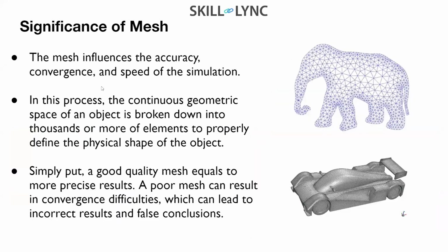Then, significance of mesh. Mesh influences your results to a very large extent, whether at the time of solving, or at the time of speeding up the simulation, or at the time of checking or validating your results with analytical or experimental data. As I said, in this process the continuous geometric space of an object is broken down into thousands of elements to properly define the physical shape of the object.